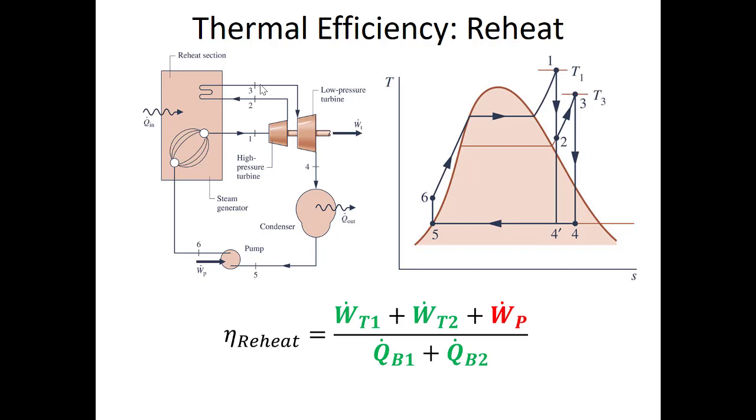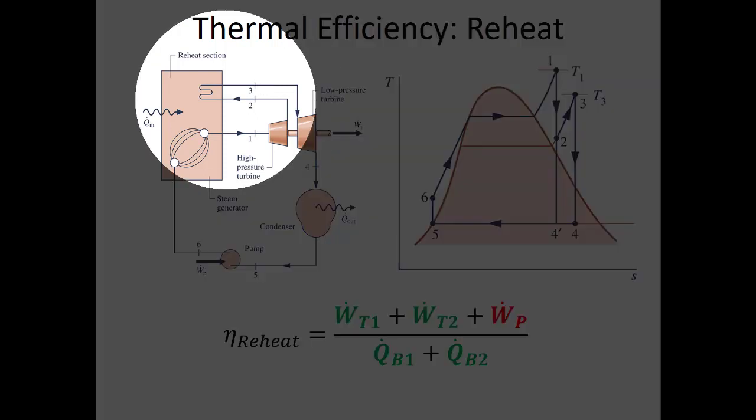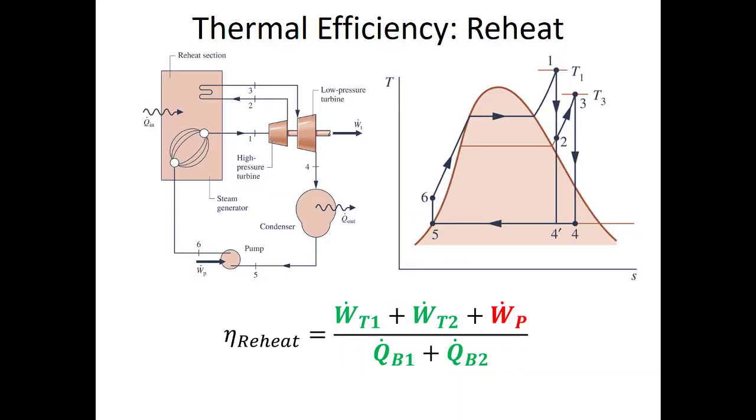So the process is generally the same as a 4-component Rankine cycle. So even though we're increasing the complexity here, the process is going to be the same. It's just we have more components, right? But if we know how to go through and systematically do a 4-component cycle, doing this reheat cycle hopefully doesn't seem all that much more confusing, except that our thermal efficiency equation is different.